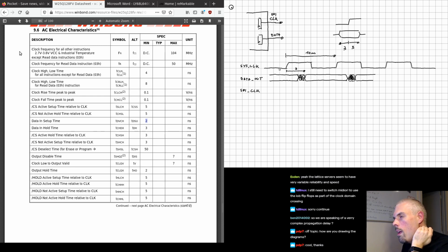So the usual way of outputting a clock from inside the FPGA to the outside is to use a DDR output register, which takes 2 inputs, one for what to output on the rising edge and one for what to output on the falling edge. And so here on the rising edge, we're going to output 0, and on the falling edge, we're going to output 1.